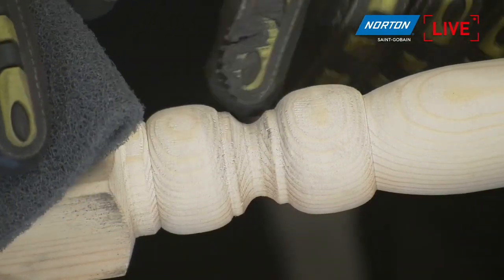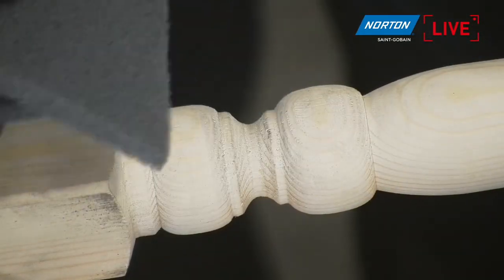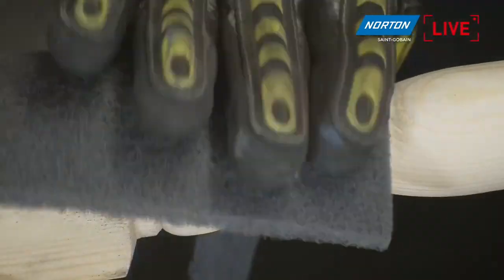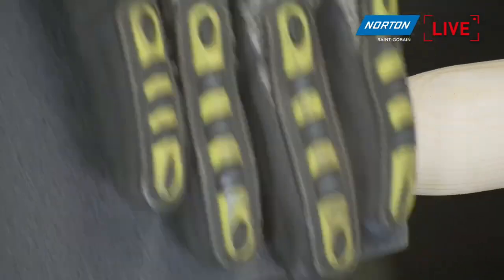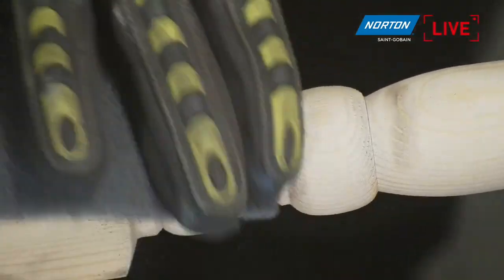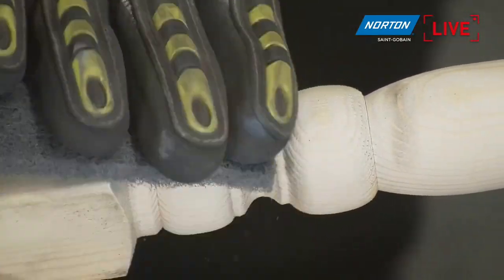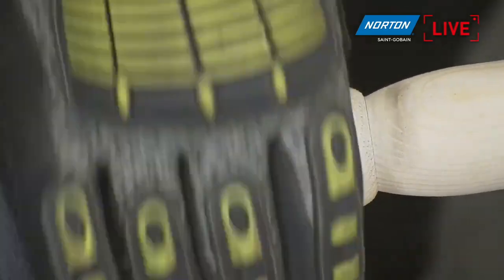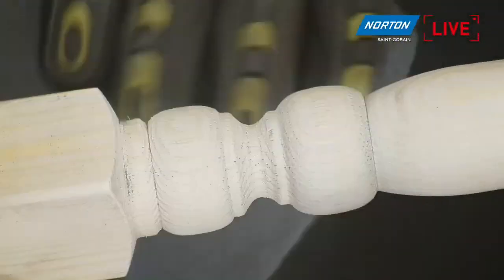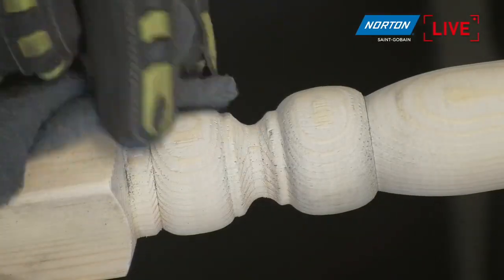And again, sandpaper is going to be really tricky to get inside these areas, but the hand pads are absolutely perfect for that, just to smooth these down before you paint. If you don't do that, like you say, you'll see all of these little witnesses of the machining marks from the wood tool when this was actually shaped on the machine, and it will not look so nice. So you can rub that around there and get a really nice flat finish on the wood, really easy with the silicon carbide. Okay, so you can see all them marks.